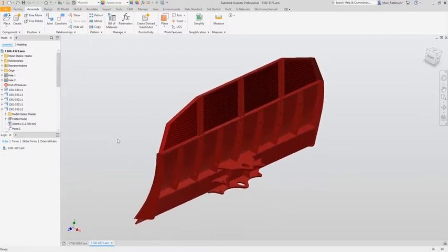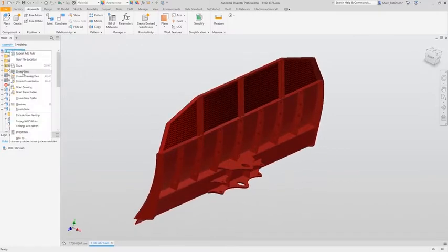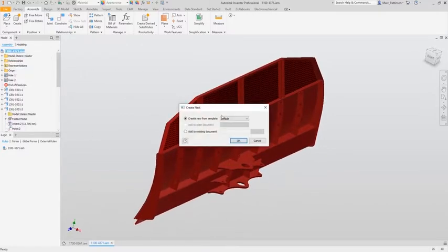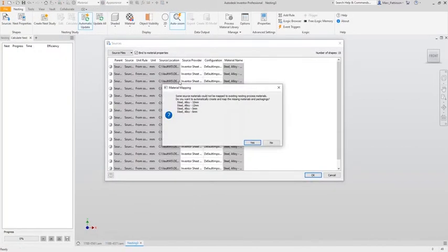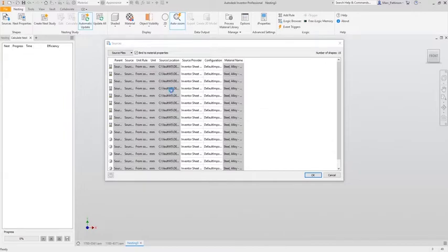There are many different ways of starting off a nested project. We're going to just right click on the assembly and start project, selecting a default template. The utility will now run through and categorize on type and thickness of the material. The nice thing once it's finished translating is that you will see each individual component in the utility, color coded depending on the material thickness.